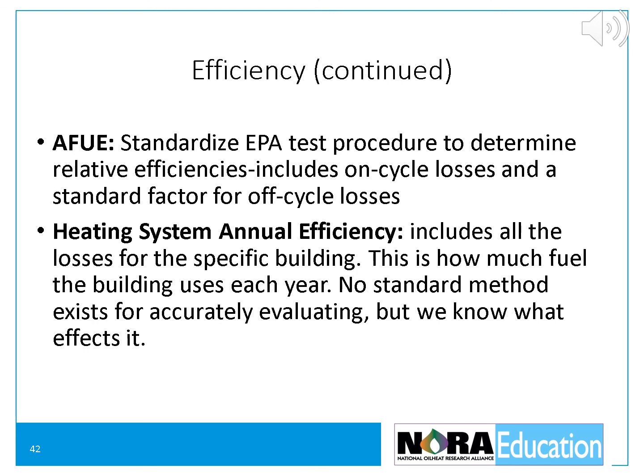Jacket losses are generally not included, even though they may be significant. AFUE is used to rate the overall efficiency of a new boiler or furnace over an average heating system for typical operating conditions. While the AFUE test cannot and does not try to take all factors that determine efficiency into account, it does give us a way to compare the relative efficiencies of the average new furnace or standard space heating only boiler. AFUE is no help when evaluating the relative efficiencies of integrated space and water heating systems.